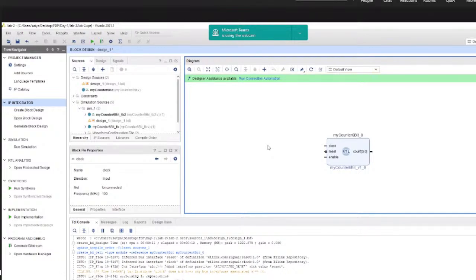The clock frequency synthesizer basically works by taking a reference clock. If you want an operating frequency which is lower than the reference clock frequency, then you have to use a clock divider. You need to divide that clock in order to get a reduced clock frequency. If you want an operating clock frequency that is greater than the reference clock, then you need to use a clock frequency multiplier. There are a few design techniques for how to design a clock frequency divider or a multiplier, and so forth, in the literature.